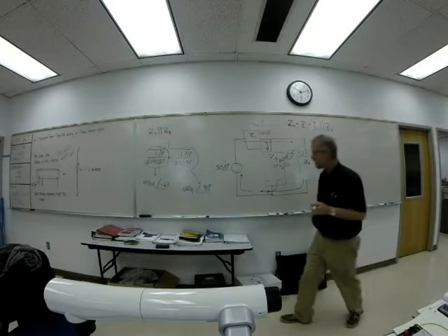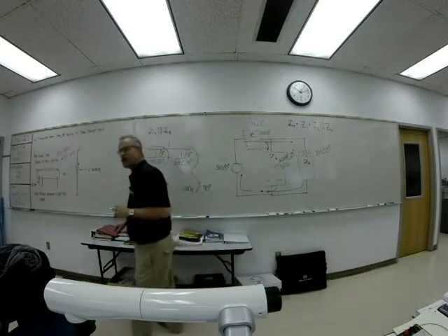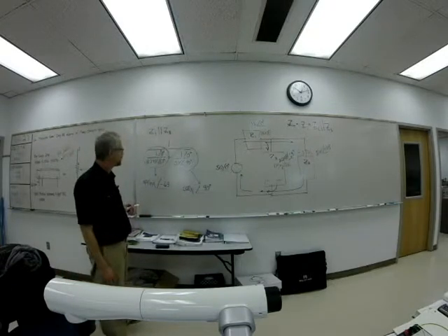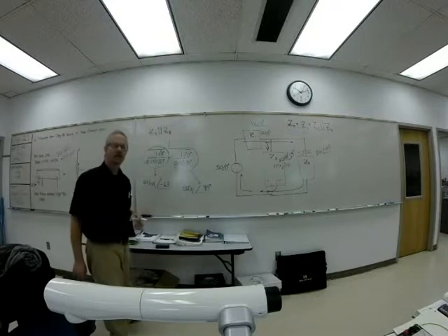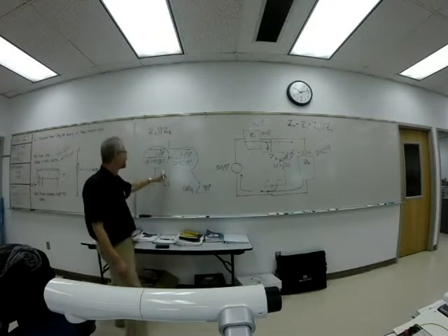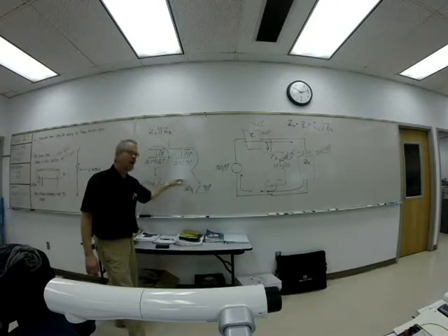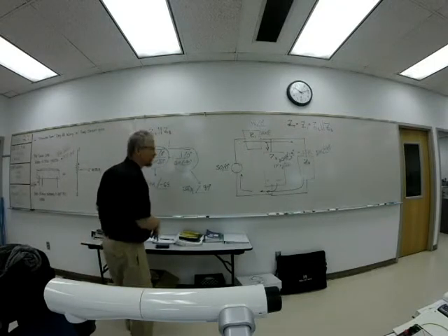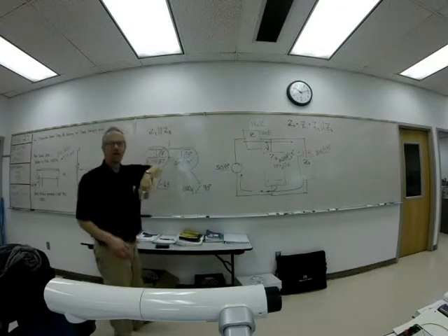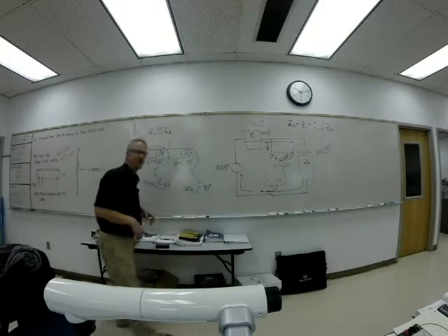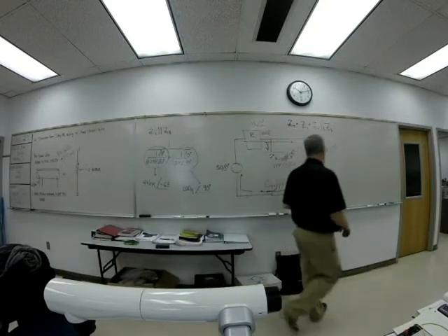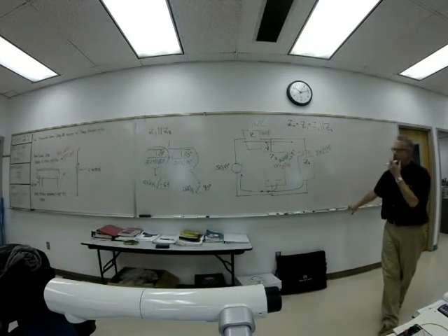Okay. Any objections to these numbers? No, then we still need to do 1 over, right? Yeah, well, we've got two things to do. Not only do we have to do the 1 over, but we do that after we add these together, which means we have to convert both of these back to rectangular, add them together, and then convert it back to polar, and then divide it into 1. So we can complain about it all we want, but we might as well just do it.